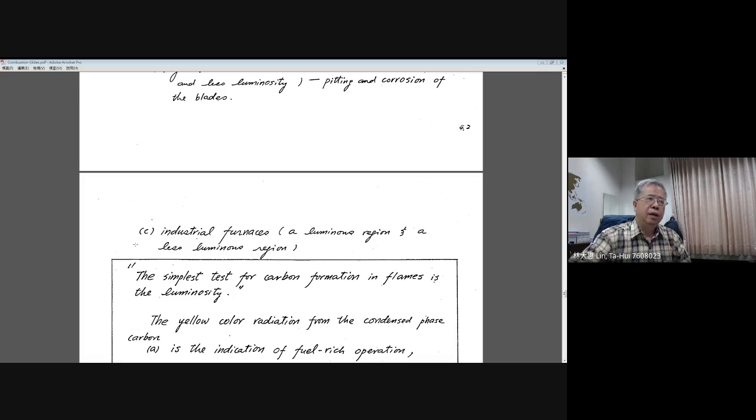This is another different thinking, because you have a large range to let your solid particles burn completely. In the primary zone, you will let the particles exist and burn as a yellow flame to have stronger radiation transfer. But in the downstream, you need to control it to burn all the particles completely and diminish the luminosity. And later on, it will be clean, I mean, clean means less particle emission out.